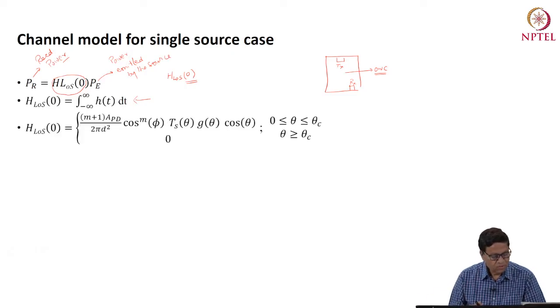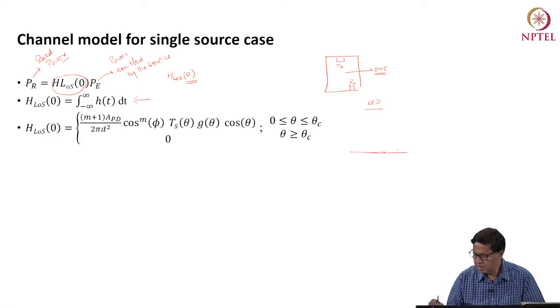So now let us try to understand how we model that optical wireless transfer function. Suppose this is your LED. This is the receiver plane, and your receiver is, say, somewhere here. This LED can have a radiation pattern depending upon the value of the Lambertian parameter M. It can be a narrow emission or a broad emission.